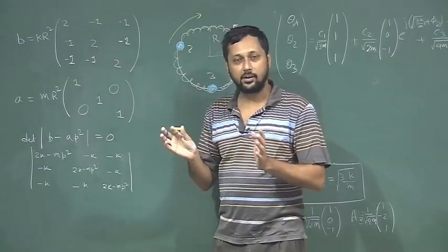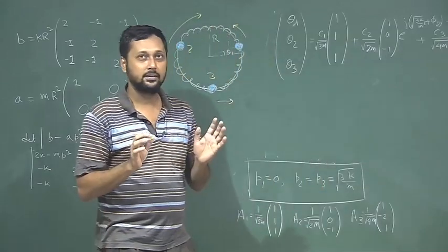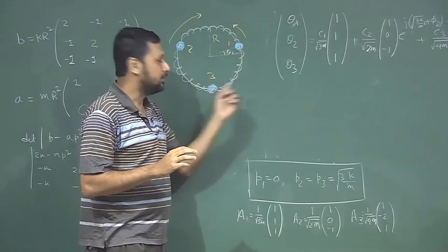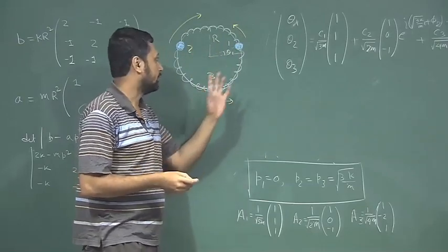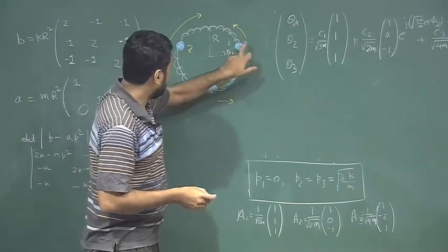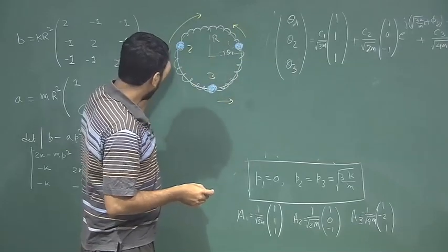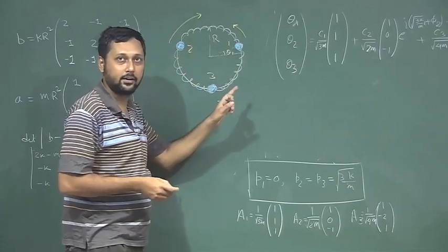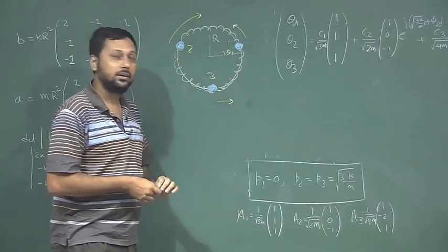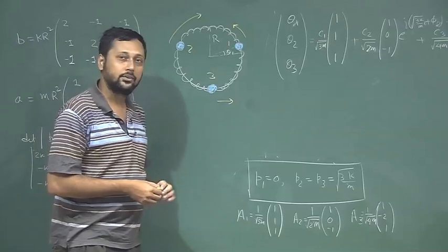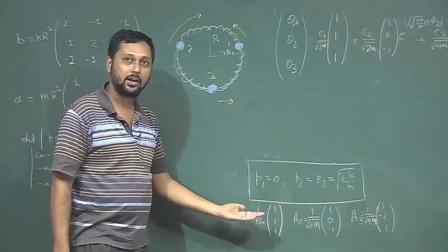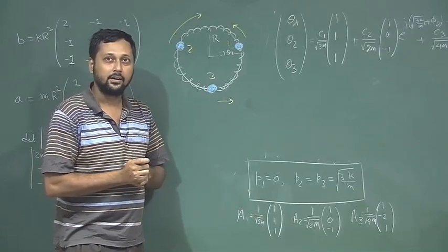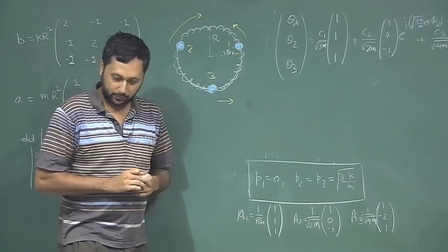So, it is a potential energy problem where every movement affects every possible potential, or rather, the movement of this one also influences the potential energy of this particular spring, although they are not directly connected. And it also gives you a very interesting concept of finding orthonormal eigenvectors, orthogonal and normalized, in a degenerate case. So that is why I chose this problem.